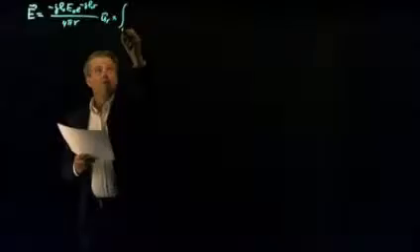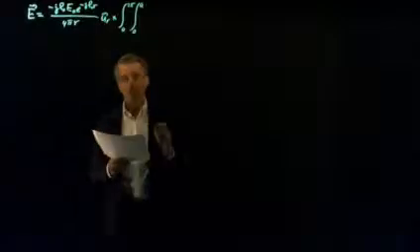Okay, so we have to integrate over the aperture. The uniform circular expression for the electric field was given by this expression, so minus j k naught E naught divided by 4 pi r. And then we have this integral over the aperture, phi from 0 to 2 pi and r from 0 to a, so the radius of the reflector.